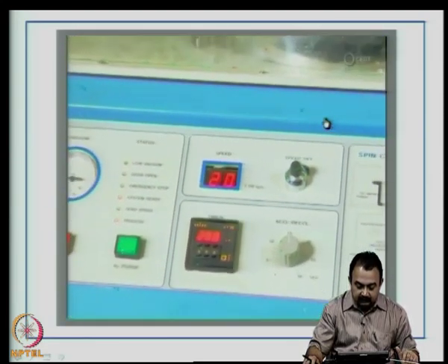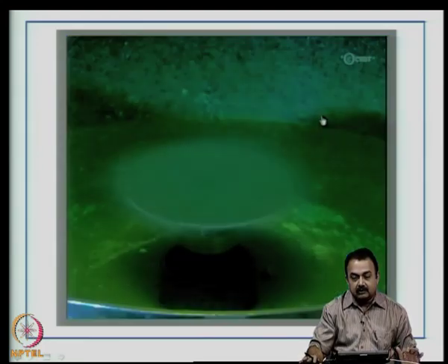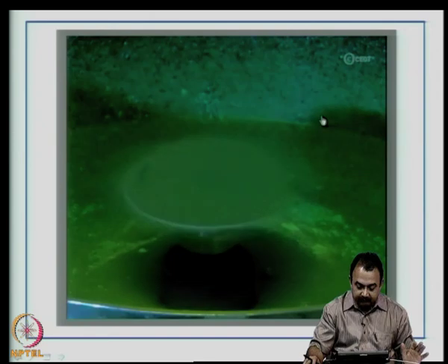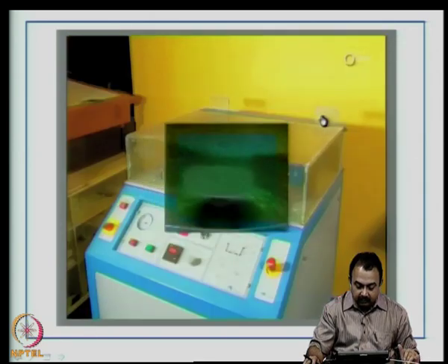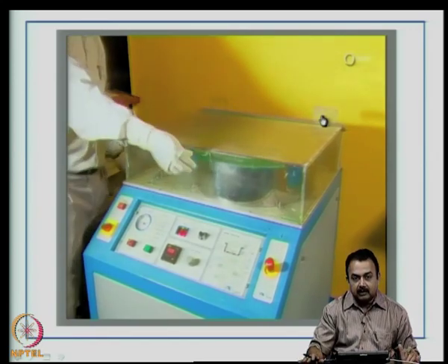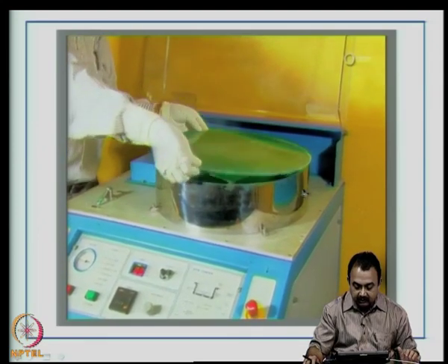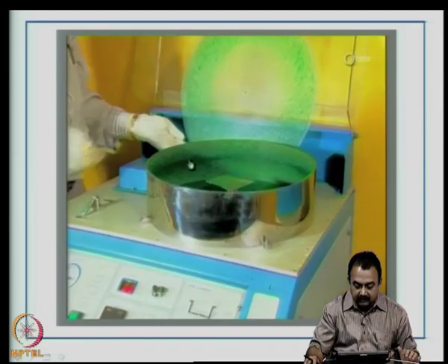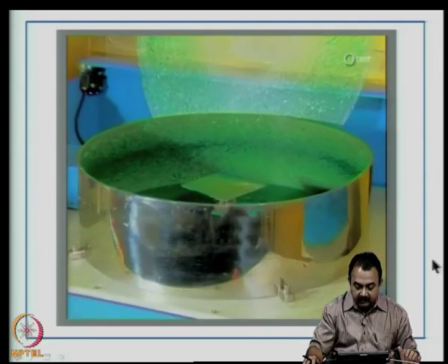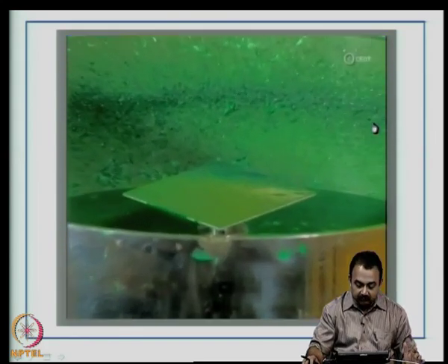The timer is also set and the material is now expected to spread all around the substrate, and you can see here a view of the spin coating. So, the excess material is now spun off outside the board area into the tray here, a stainless steel tray. So, thorough cleaning of this is also required. So, the maintenance of this equipment is also key, because if you are going to use a different material for example, then there should be no cross contamination of the materials from this spin coater.